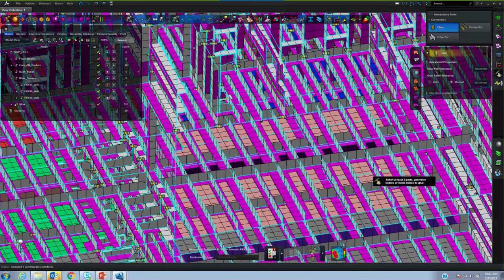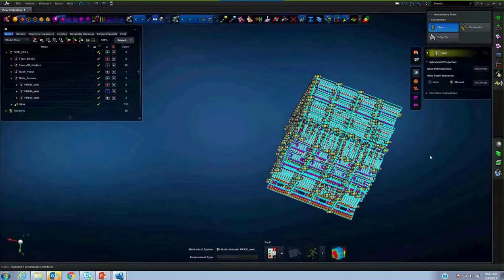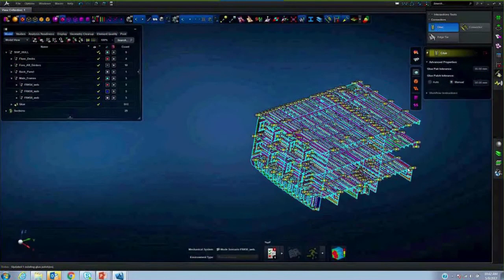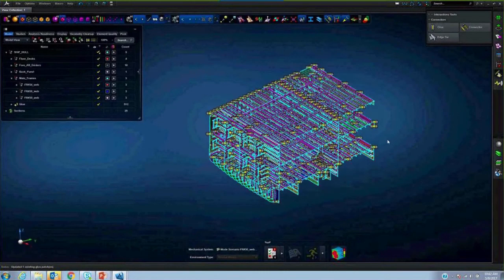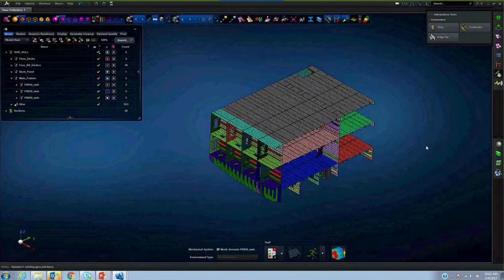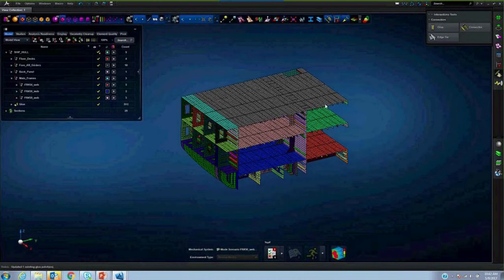All right. Now I believe all the parts in this model are assembled using glue. So what is next? The next thing is to apply the loads and boundary condition for this model so that we can run a simulation. In this model, what I'm going to do is apply some kind of pressure load on each of those floors and then constrain the rest of the model, depending on how this model is connected to the rest of the model or how the overall boundary condition is created.